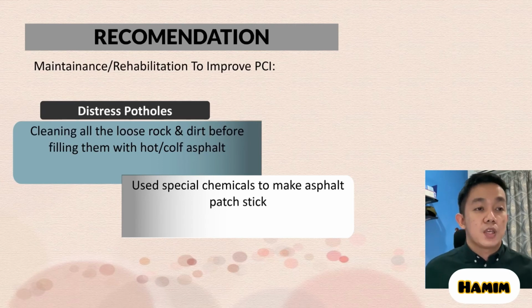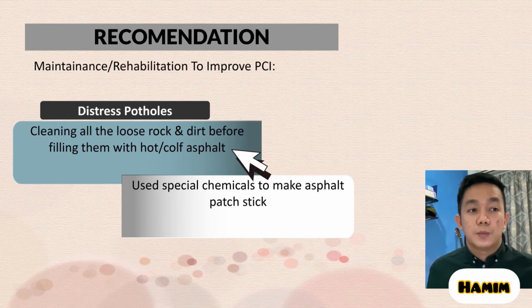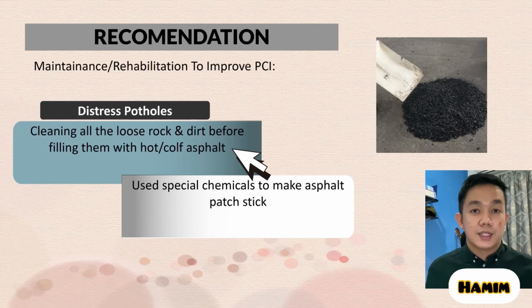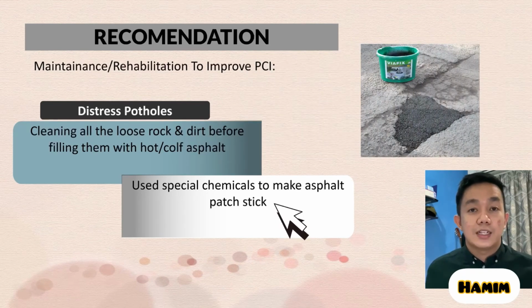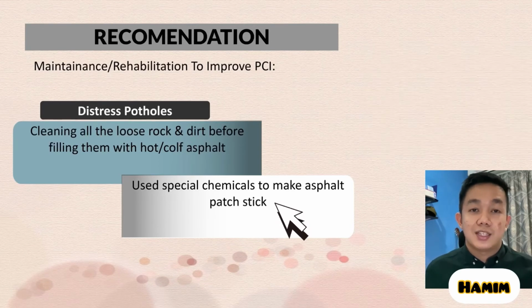Today, I want to explain to you about the recommendations for our road project. Okay, the first recommendation is for distress pothole. We must clean all the loose rock and dirt before filling them with hot asphalt. Second, we must use special chemicals to make the asphalt stick.